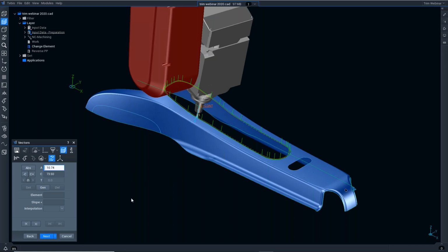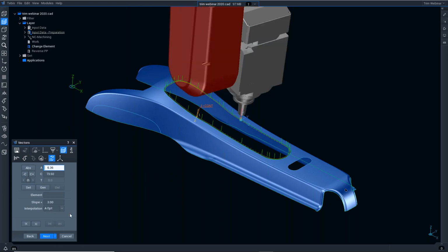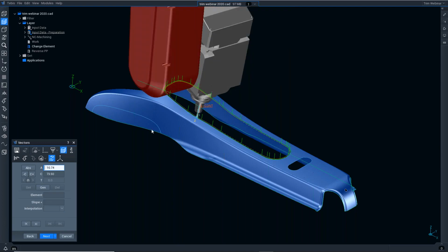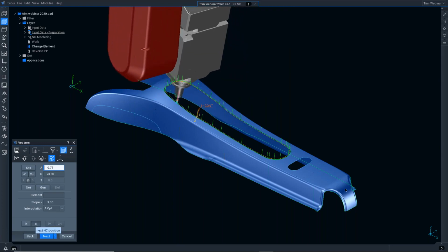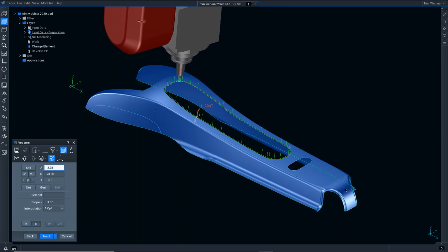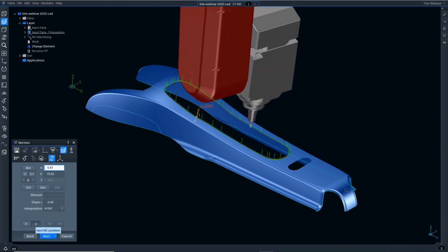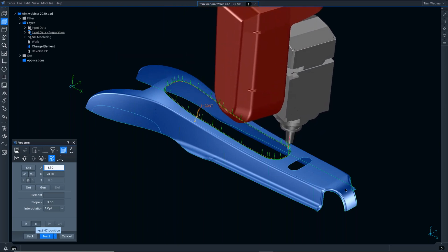So if we tie those two angles together, so the tool starts and finishes in the same position, and then go over to an area on the curve, we're going to do an A optimized toolpath. This will now prioritize the A movement over C movement. And what we should get is a nice movement with only the A axis moving. So that's tidied up the path an awful lot and should give us a much better result with a finished component.